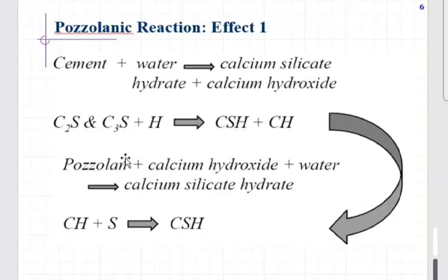But to activate these supplementary cementitious materials and pozzolans, some activator is needed. So what we do over here, we add a partial amount of them into the cement as a replacement, and then we see how efficiently we can use them in the cement. So this is the philosophy behind it. Are we clear? This is the reason we call them supplementary cementitious materials. So they supplement the cementitious properties.